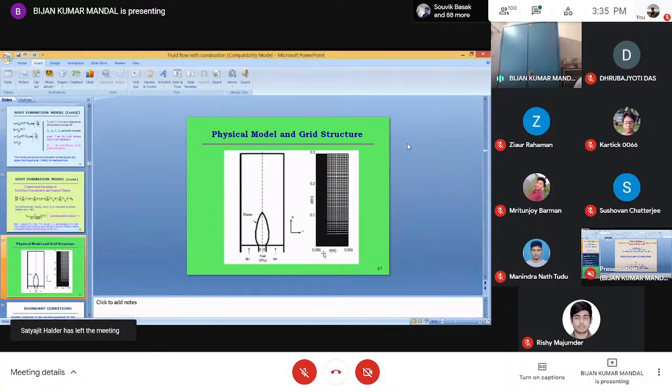Now, as the number of grids increases, you can see that it means a fine grid, that is, very close grids. The accuracy will be better, but the computational time will increase. Then you have to take an optimum size. And obviously, if we simulate both sides together, it will be simply double. Since it is exactly the same, there is no need of doing that.